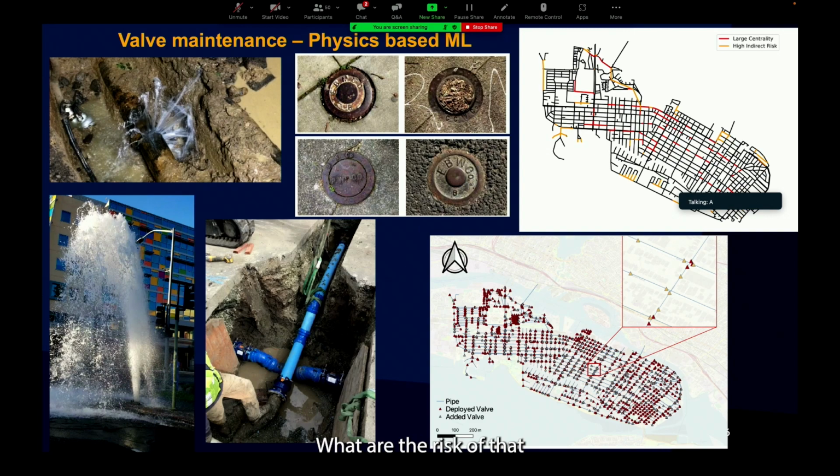What are the risks of that particular condition? And once you do the simulation, actually it's not a very easy simulation, because you look at each valve or combination of the valves, and you can see how the water network is associated. And then if you do a brute force analysis of every valve that you see in the Alameda Island, you see that each simulation of the water network takes about 1 second, and if you look at all the combinations, probably it takes about 100 years to do the simulations.